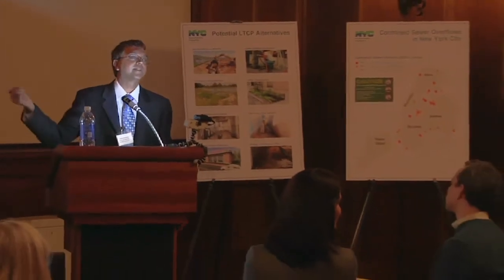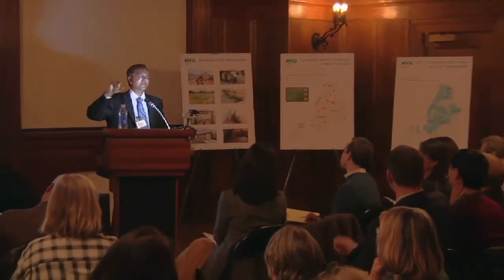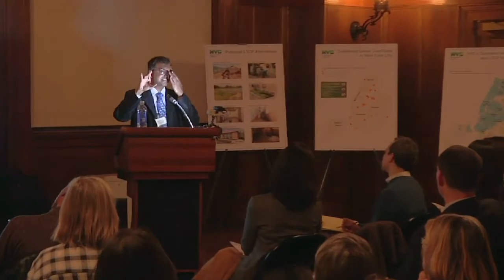Yeah. Well, the thing is, I skipped a slide on the detailed model parameterization for the 3 distinct surfaces that we talked about, and how those are varied based on the density of single-family residential, as well as the presence of larger pervious areas and so on. But I can share with you, Paul, on the details. Yes, it is in the model calibration report that's being reviewed by DEC at this time. Once we have that in final form, or even before that, I can share with you.